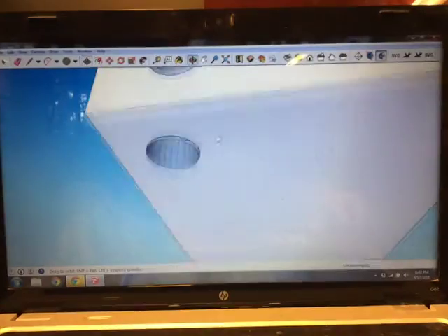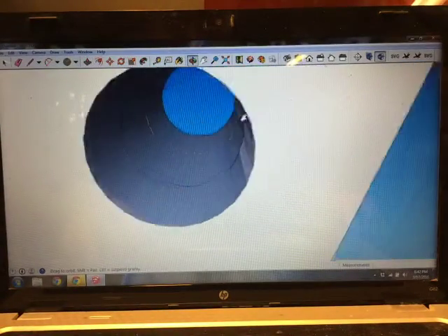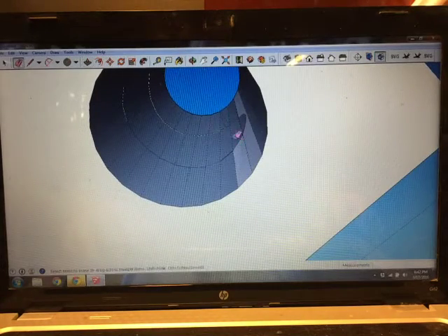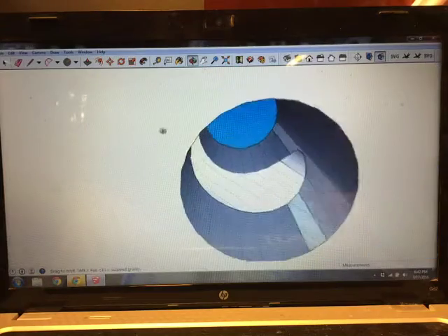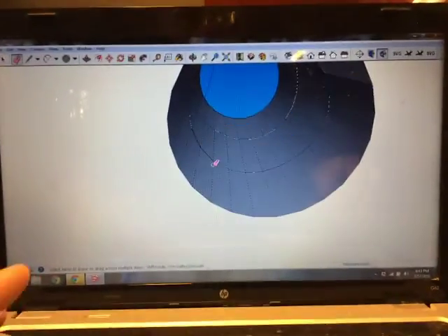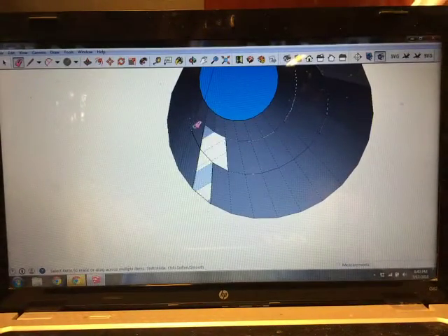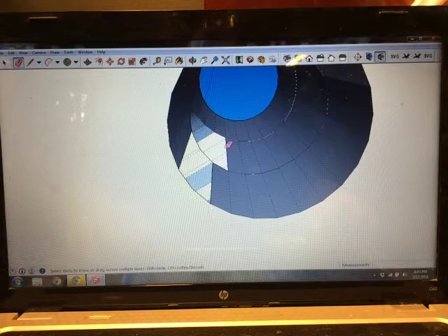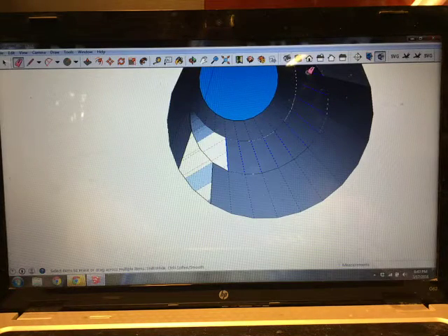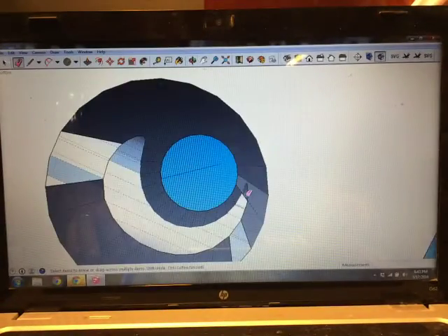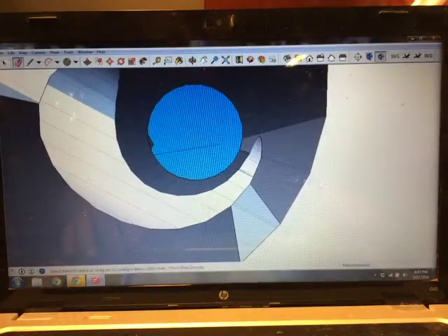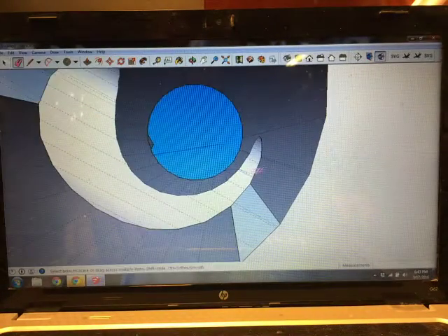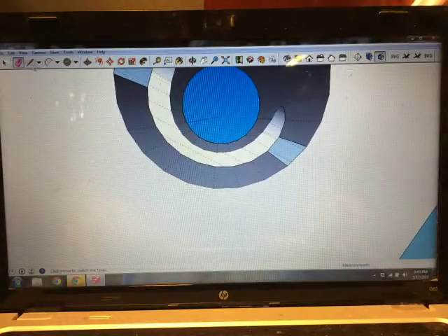Orient Faces. Okay. So when I oriented the faces, there was like this on-off going on. It doesn't know what to do is what it comes down to. It's got two faces that don't make sense to itself. And it looks like we had a problem with a double line existing too close. So kind of like that double line there. Let's Orient Faces. I bet it'll clean up. Yeah, most of that cleaned up.